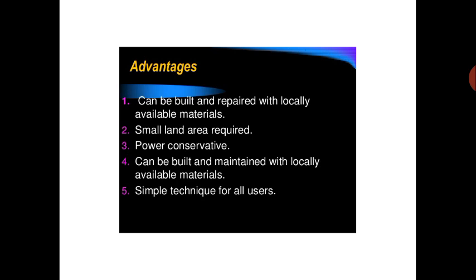Some demolition waste from buildings can also be used in this soak pit, which have a higher life. Make sure that when you are using any of the materials, the organic content of the materials you are using in the soak pit should be very low, 3 or 4%. Only that much is required. It only has to absorb, it should not degrade.